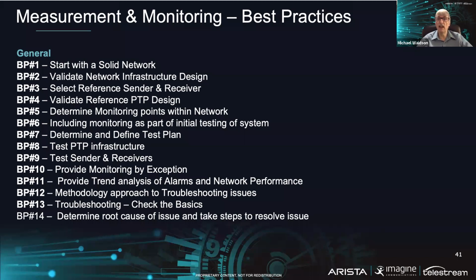So we've outlined areas where you might consider an ingest or transmission to put your monitoring points, but you might also have them dotted around the whole of the broadcast center, looking in QC or edit areas or in the master control room. As you build out your system, you want to define and determine your test plan. So know what you're going to test and how you're going to validate those tests to make sure your device conforms to its specifications. You're going to be testing the PTP infrastructure.